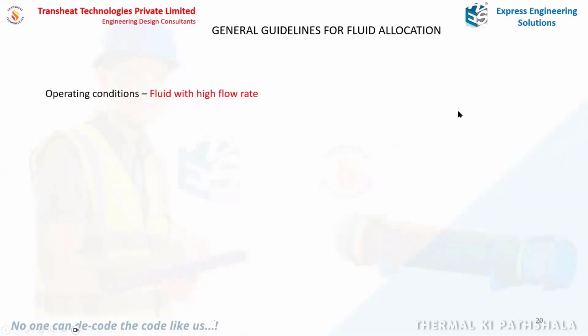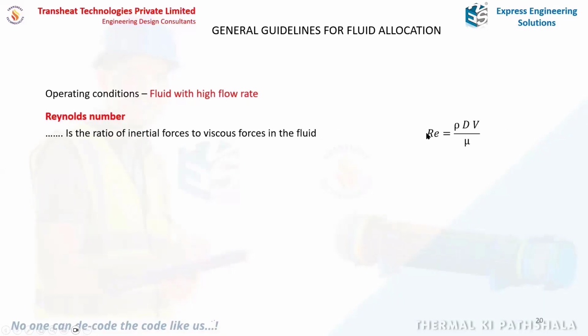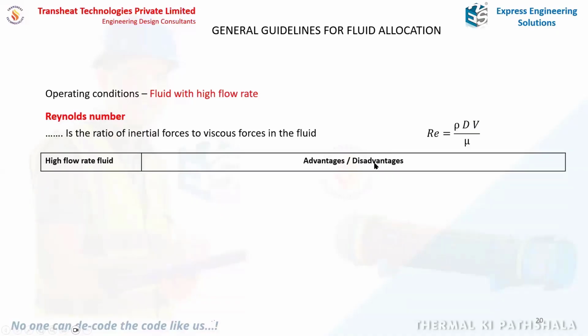Okay. Now what do we do with a fluid with a high flow rate? Again, as with viscosity, it's the Reynolds number which will influence our decision on where to place a fluid with a high velocity. Once we are saying a fluid with a high flow rate, it generally also means that we have a reasonably good velocity for that fluid. So your Reynolds number would already be a bit higher. So what would you do in such a case? Where would you locate it?